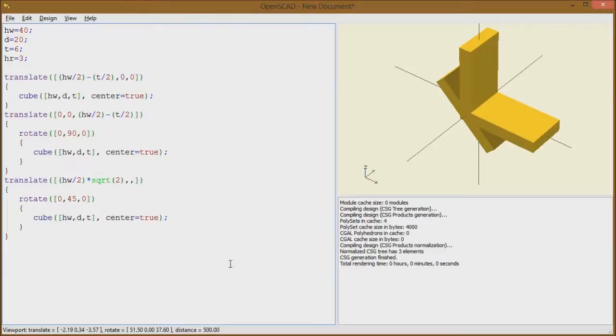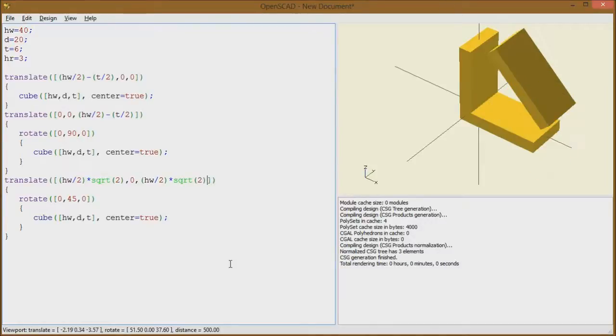And if we do that, okay, and let's do zeros for now. If we do that, we're getting placed way over there. And we'll want to do the same thing for our Z parameter. So again, let's do height width divided by 2 times the square root of 2. And we'll see it's not quite in the right place. So what we do then, because that's about double what we need, we can divide by 2 and divide by 2. I like just tying up my brackets to be absolutely sure we're applying the right thing to the right place.